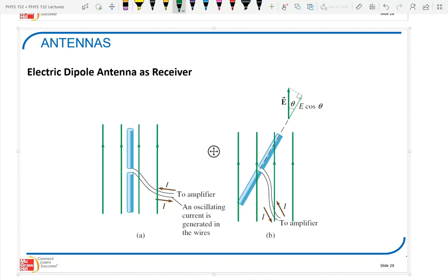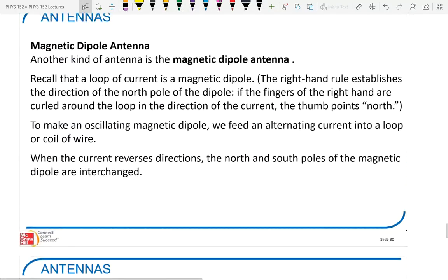Now, most of us would say, okay, take my grandmother's case. That was a vertical antenna. I should probably have my antenna vertical to match it. There is a little bit of problem. The Earth's surface being curved and whatnot, the direction can be rotated some depending on where you are, and based on the topography as well. So that's why you can't just simply say, okay, make it vertical and make this one going out perpendicular to the direction and we should be good. It's not so simple.